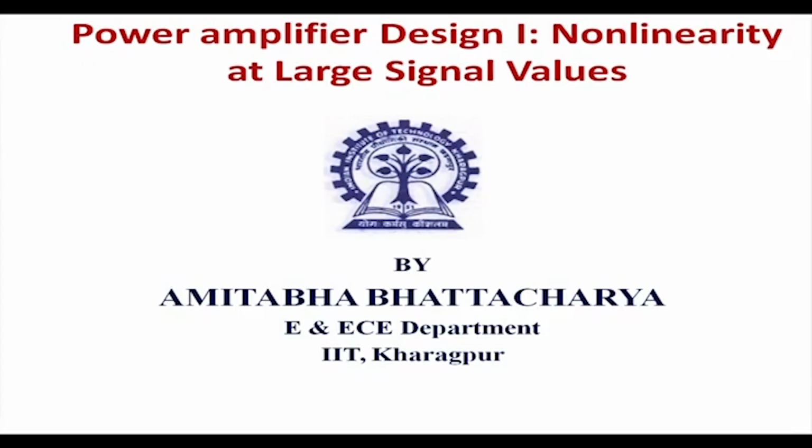If we do not restrict ourselves within those constraints, then due to nonlinearity we generate some other spurious frequencies, etc. Also we saturate the amplifier, so its gain falls. So, it is essential to understand power amplifier nonlinearities. That we will see in this first lecture. Actually, the next 2-3 lectures will be on this.